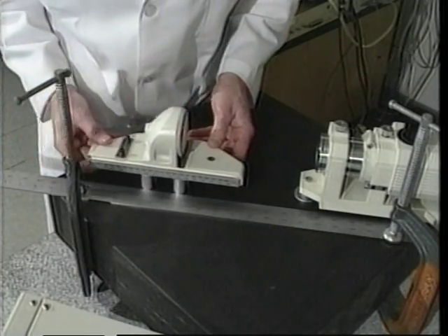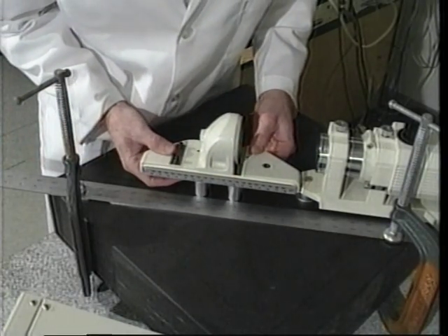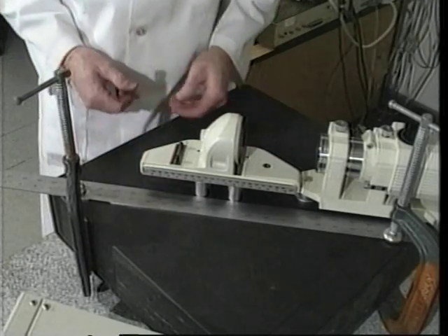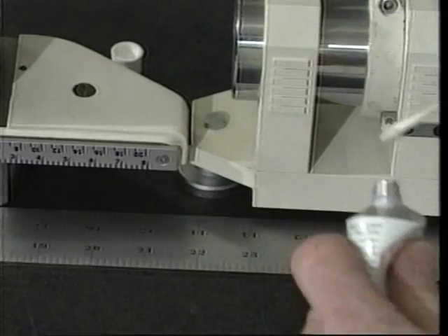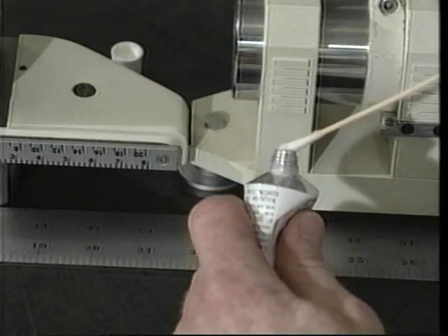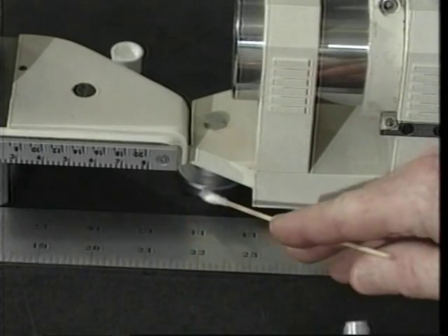Return the reflector to the initial measurement position and verify that the alignment there is still within the allowable limits. When the alignment of the optical unit is complete, secure the foot pads with wax or some other temporary adhesive.